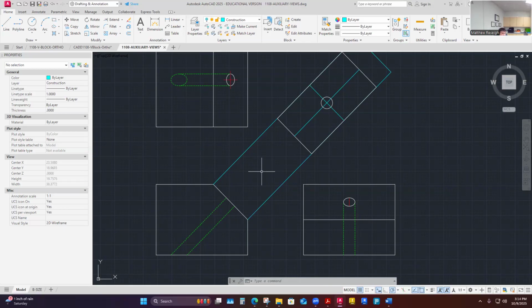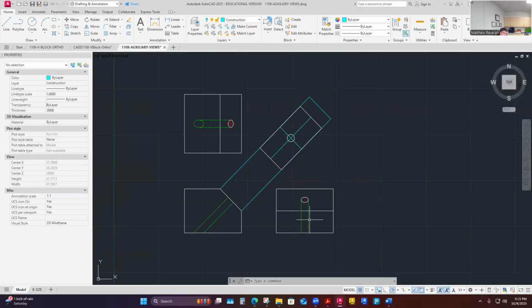And we're going to do the same thing with this weird sloped surface and where the hole actually is on the part. So if I project from it, using my glass box method, and almost add a new viewing plane to my glass box, it's not just those simple six sides that every shape has. Now this shape has some features where I can project from. So I'm going to project a new surface plane from that, and I'm going to restrict it like I would with the right side view and top view.